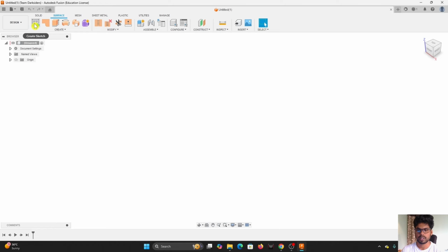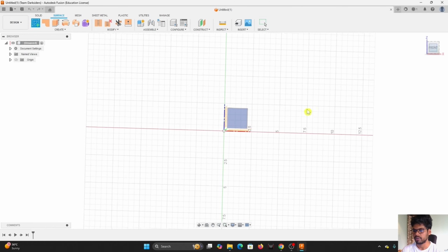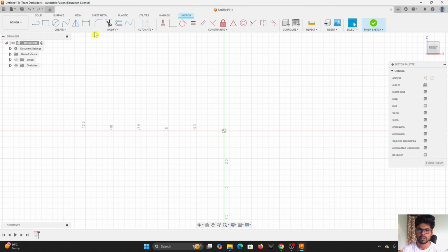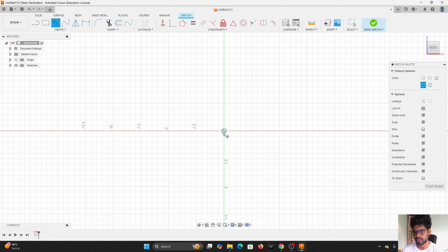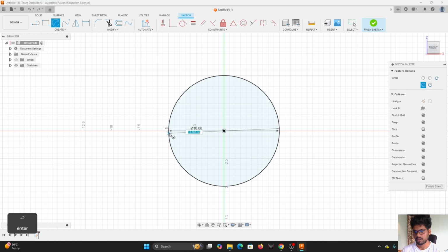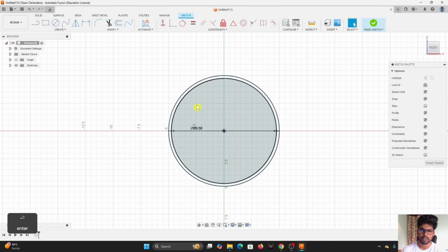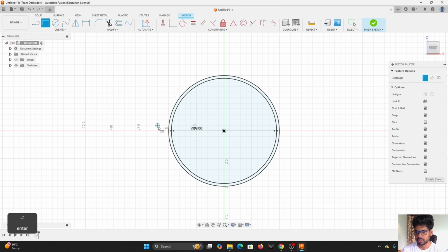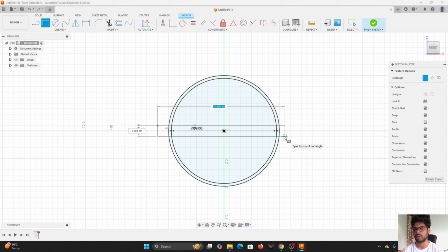So let's start with creating a sketch in the front view. Let me select that. Okay. And we need a couple of circles to form the Pokeball outline. Let's make it about 10. And another one, 9. No, let's make it 9.5. Seems about right. Also, I'll just make a simple rectangle to divide the Pokeball shells like the red and the white one. So that would do.